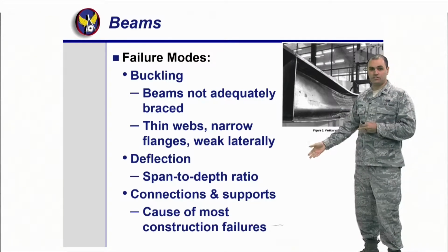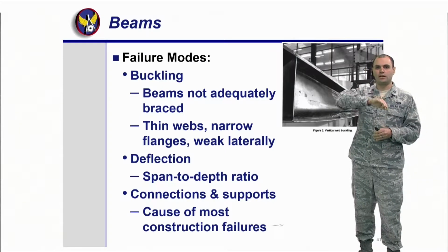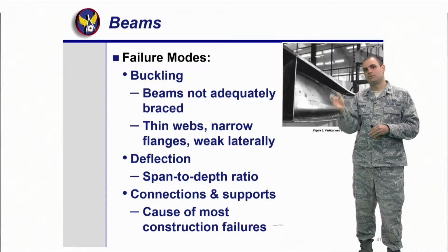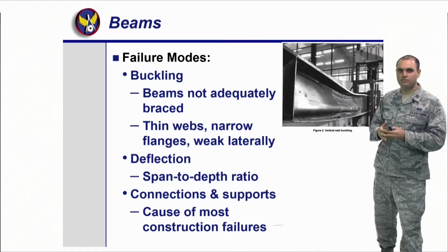The other one is the deflection, right? So when you see steel, a lot of times you see it kind of camber up, right? Instead of being deflected to the bottom, it's deflecting to the top. Why? That's just how it kind of comes out of the fabrication, so you've got to account for that.